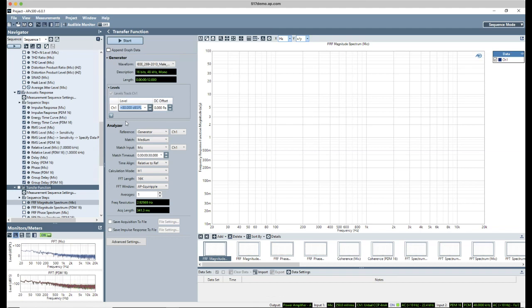That's a little bit long explanation, but the short is this signal has a much higher crest factor than a sine wave, so I need to boost this output actually to get the signal level I expect. We're just a little short on time, so I won't go through the process of finding and setting that. We might do a separate blog post on that, but I'll go ahead and just put this to 114 dB SPL, which is calibrated against a sine wave to get the signal level I want.